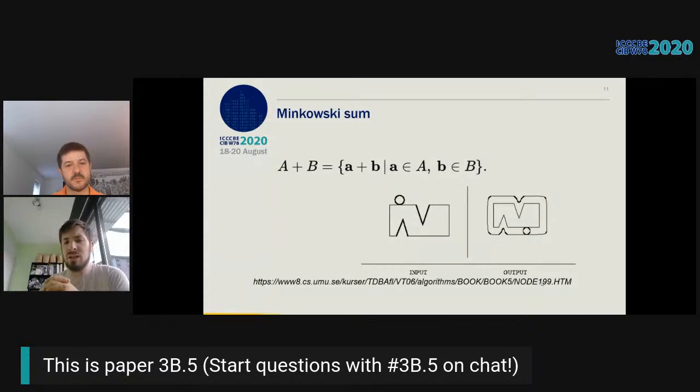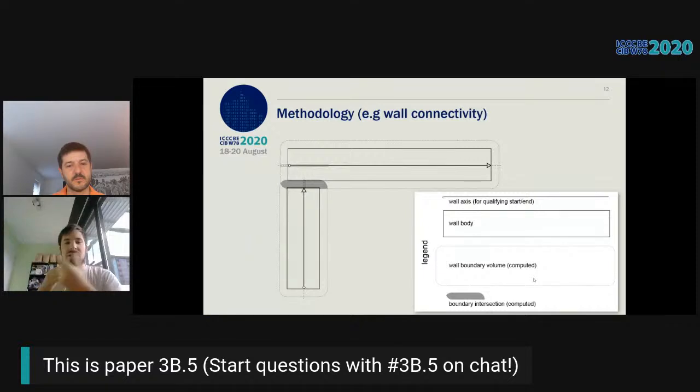And this boundary we consider as the Minkowski sum of, let's say, the operand volume, the operand surface, and a small volume. And this creates a narrow, hollow solid along the exterior of your volume that you can use to intersect with other elements. Here, for example, you see that illustrated in the case of our wall connectivity connection.